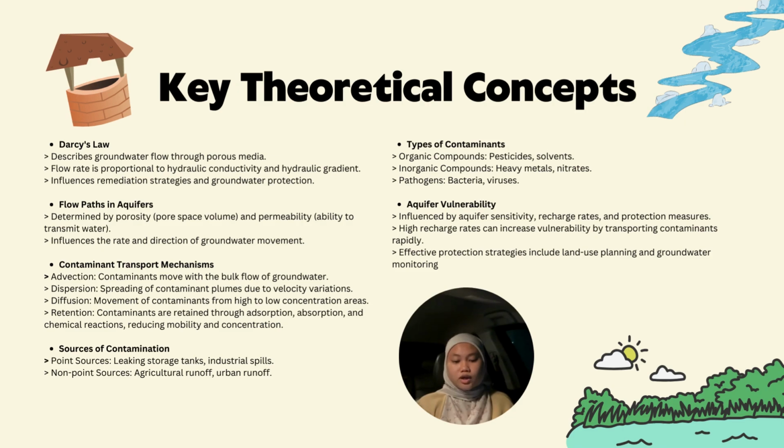Aquifer vulnerability, which is influenced by aquifer sensitivity, recharge rate and protection measures. A high recharge rate can increase vulnerability by transporting contaminants rapidly. And the last one is effective protection strategies, which include land use planning and groundwater monitoring.